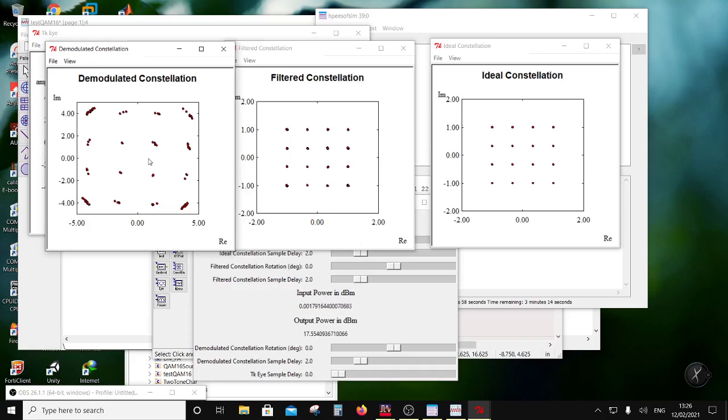So you have understood the moral of the story: in a system, it's not just the linearity of the PA. It is also going to be the phase noise which will come in. And remember that the PA which we are using is an ideal model which doesn't have phase modulation, so it doesn't have AM-PM conversion. So when you put your practical PA here, you will see more variations, right? So this is an optimistic result that you are seeing here. That's why it is looking so nice. But in real systems, it's going to be much worse than what you are seeing here.